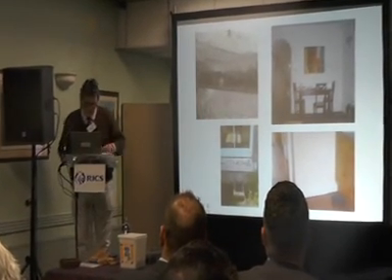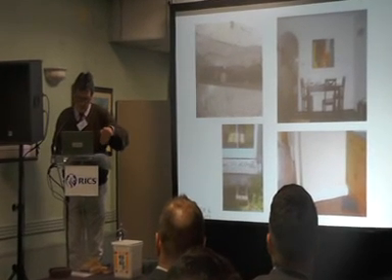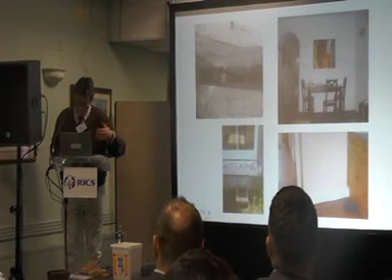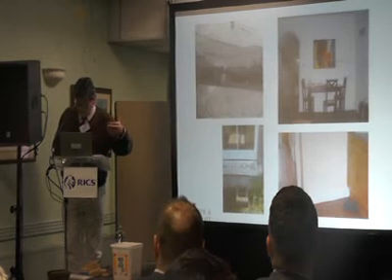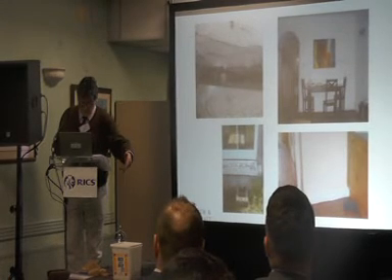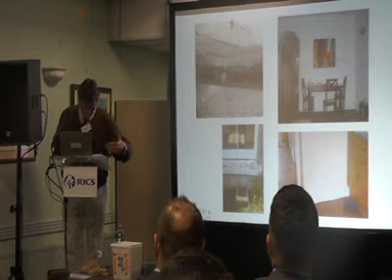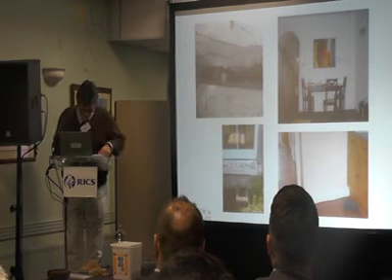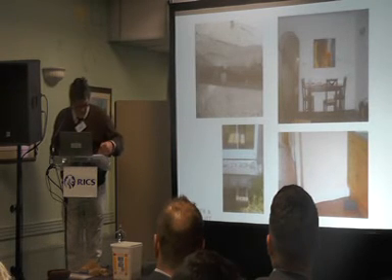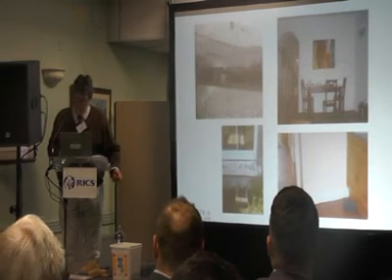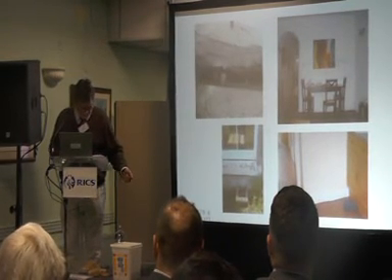Now here's a great one. Top left, I'm looking down from a roof between a wall and the strappings on the inside, and I'm seeing material dropping down and bridging. At the skirting board level, down at the ground floor, that's going to be a mess. It's going to bring moisture straight across and into the building, and sure enough it does. The picture below that, the floor inside is below the ground. The vent is below the ground.